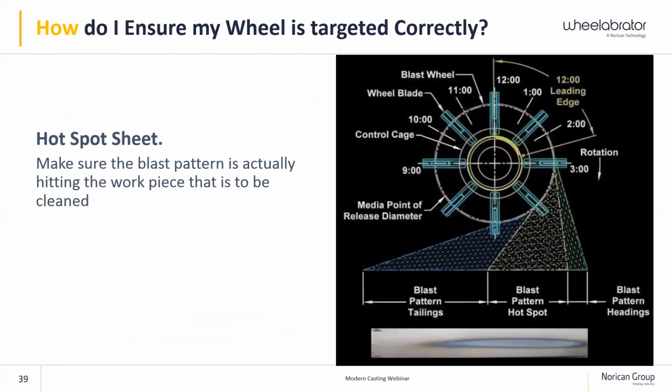There's no mistaking where your pattern may be aimed at when you see that. You will know dead on where your pattern is. They should always look nice and cylindrical like that, elliptical, excuse me. If you ever see it chopped off to where one end, the right end or the left end, all of a sudden is bull-nosed or flat off, that means you're probably bouncing off of an inliner or something else before it actually reaches your part. It's going to wear components out faster.